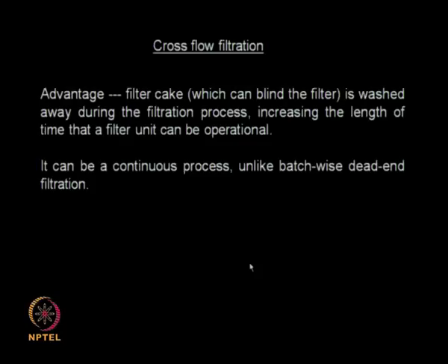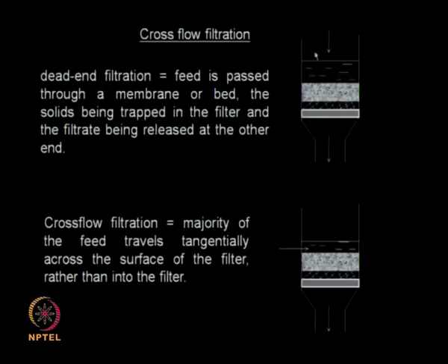So what are the advantages of this? As you can see, in the normal approach your bed is sitting on top of the filter medium, so it slowly blocks the holes and your filtration process stops. Whereas in crossflow, because the liquid is flowing like this, it washes the solids that settle on top of the filter medium. So it prevents the clogging of the solids.